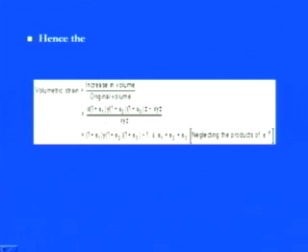Now put in those values which we got in the previous figure: x times 1 plus epsilon 1, y times 1 plus epsilon 2, z times 1 plus epsilon 3, divided by xyz, which is the original volume, will give you the volumetric strain. So we get 1 plus epsilon 1 into 1 plus epsilon 2 into 1 plus epsilon 3 giving the volumetric strain. Or, since these epsilon 1, epsilon 2, epsilon 3 are very small amounts.